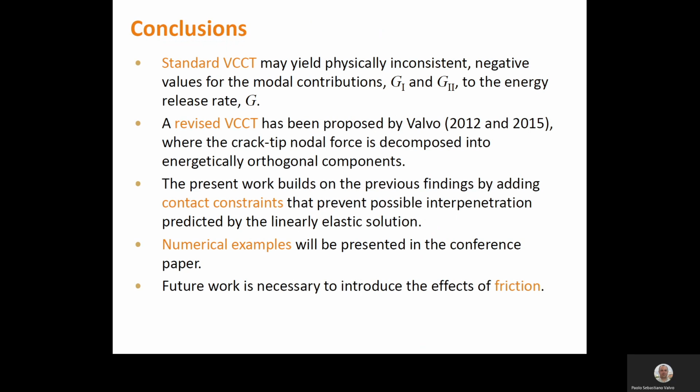To conclude, we have recalled how the standard VCCT may yield physically unacceptable, inconsistent negative values for G1 and G2, and a revised physically consistent VCCT has been proposed in previous papers, where the crack tip nodal force was decomposed into energetically orthogonal components.